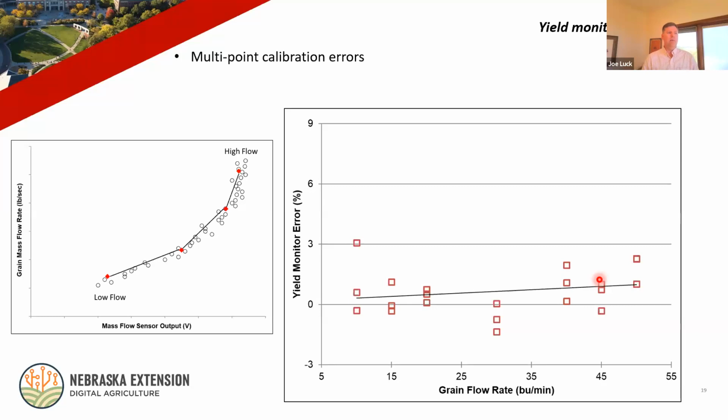I don't think we see quite the same with the volumetric systems, but remember, with volumetric systems we're actually calibrating back to weight. So even with the volume-based systems, you're running a calibration load and you're weighing it. That makes that one a little bit more complicated, in my opinion, because of the test weight. The only other real quick thing I would say there is technology like Active Yield from John Deere. A lot of folks are seeing that out there now, where the bin on the combine has some load cells that are capturing calibration weights.